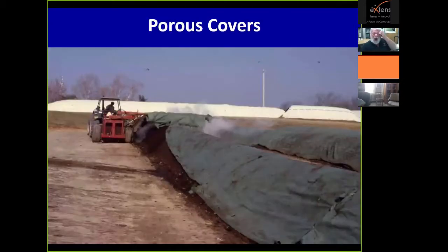So here we see the polyethylene fleece cover. You see the roll-up, the wind-up roll here. The system is set up so that as he traverses down the long axis of the windrow turning it, his take-up reel will wind the cover up on the reel. He can turn the windrow and then unspool the cover back over the pile.